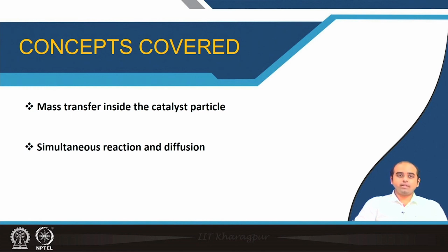We made an assumption that at steady state the rate of disappearance at the particle surface should be equal to the rate of flux convected towards the surface. We also said that the particle surface concentration is significantly lower compared to the bulk concentration, because generally the reaction dynamics are much faster compared to the bulk scale diffusion.